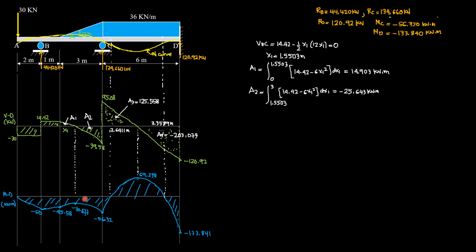So for this part, the elastic curve is concave down. So from A to this point, concave down, in fact up to here, concave down. This is the elastic curve through the support because the supports do not settle. Then up to here. Then here, positive moment means concave up elastic curve. Then here, negative moment, concave down elastic curve through the support. So that's it for this video. I hope that you were able to follow the explanation and the solutions.